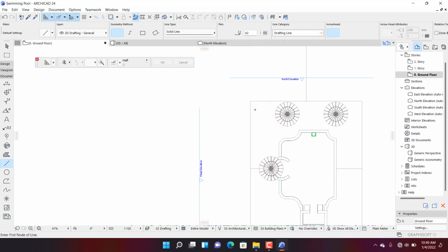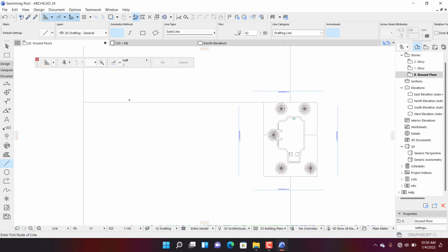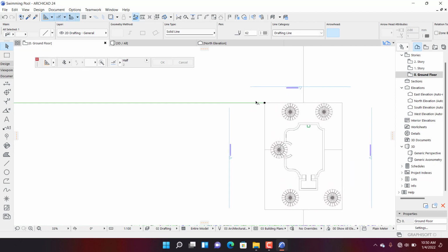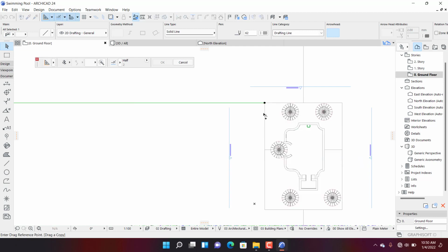So then I think you need to have a path, so I'm going to draw a path or a road, a small section where you can easily walk. After drawing that one, I'm just going to use Ctrl Shift D to make a copy of it. Drag a copy. Then we drag a copy by 1200. 1200 is okay for a footpath.